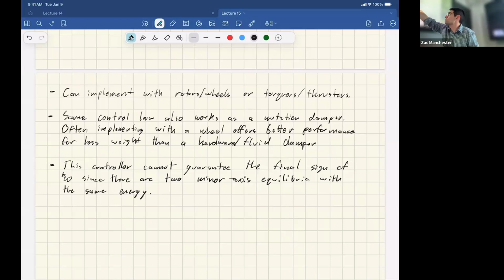So here, this U is the force applied by each thruster. And then if I map it through this Jacobian, it's going to be the total torque applied by all of the thrusters added together. Okay. So that's thrusters. Now we can do a similar thing for reaction wheels.